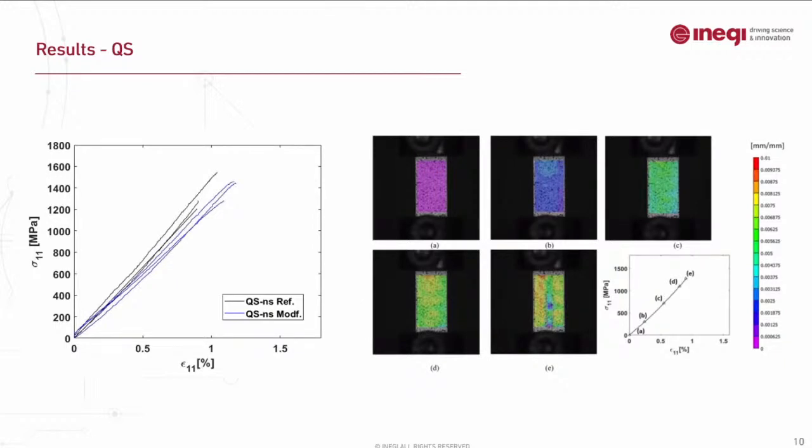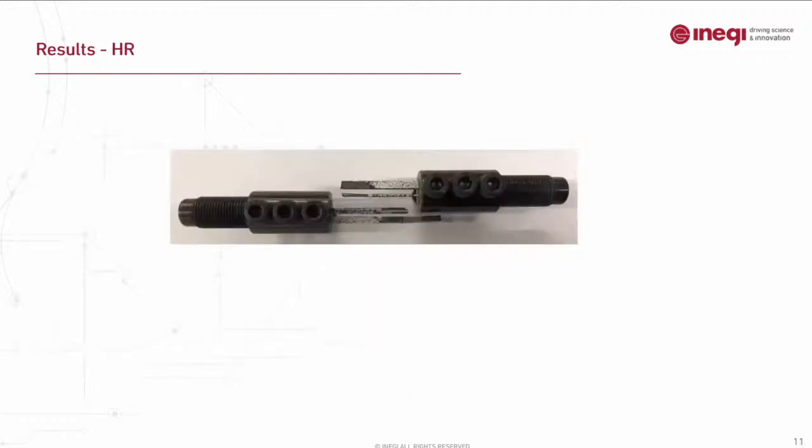Basically, with the modification that we performed, there is no rate dependence. There is no influence on the material. We only saw an 18% decline in the longitudinal tensile properties of this material. And here is the failure mode of the specimen. They all failed in the longitudinal direction by splitting along the loading direction, regardless of the modification or loading rate.